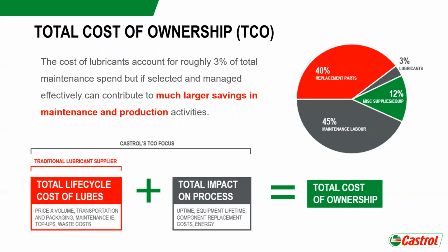If speeds and temperatures, loads have changed since the equipment was installed, and that's quite likely because most production units are designed to have a bit of spare capacity, but then once the units get older, capacity goes up even further, and the equipment is running beyond its designed capacity, but the lubrication requirements aren't seen as that important in general.